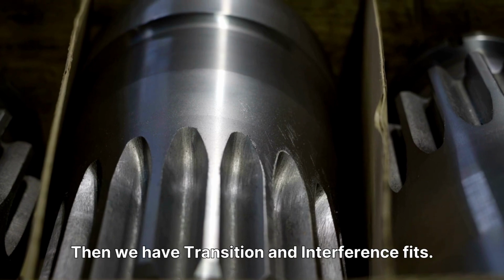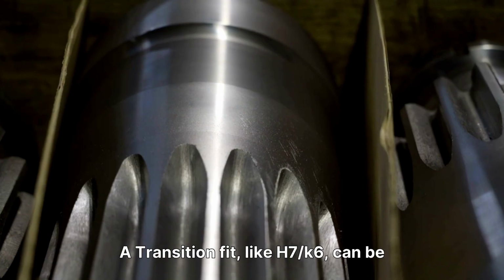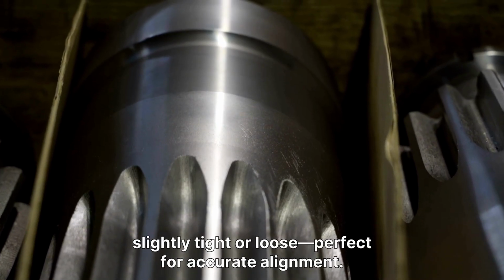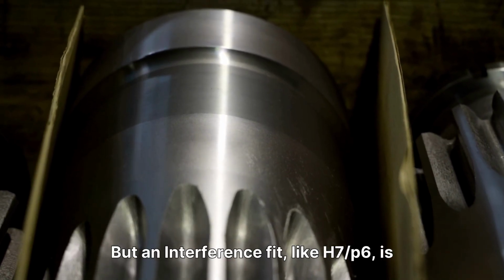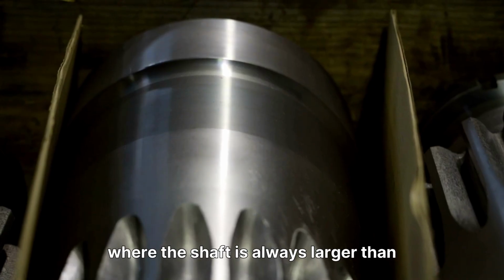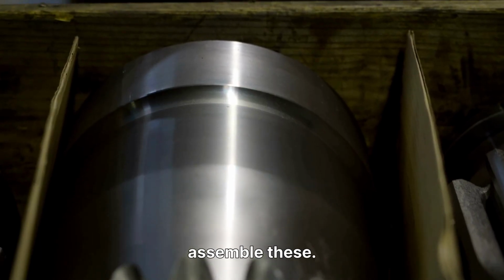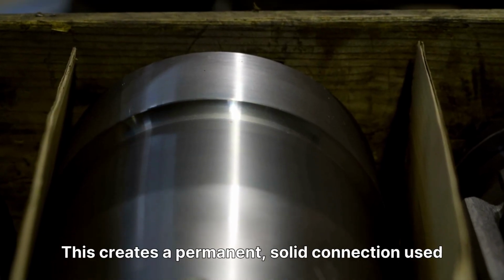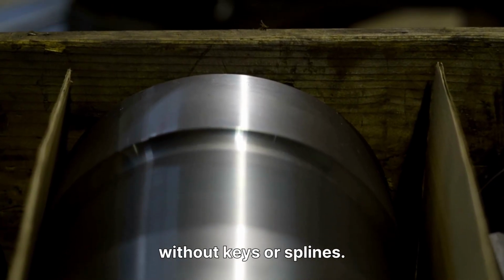Then we have transition and interference fits. A transition fit, like H7/k6, can be slightly tight or loose, perfect for accurate alignment. But an interference fit, like H7/p6, is where the shaft is always larger than the hole. You need force or temperature changes to assemble these. This creates a permanent, solid connection used for mounting gears or pulleys onto shafts without keys or splines.